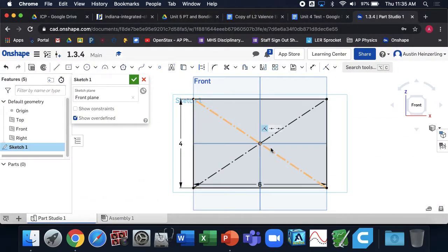How? Exactly, I just explained that. No, like, how to make the line? Yes, I just explained you could either draw a line from corner to corner, but you're like, oh crap, I don't want an actual line, so I'm going to select it and change it to construction. Oh, see, now that makes sense. The other thing you can do is say, everything I'm drawing right now, my construction line tool is activated, so everything I'm doing is a construction line. Bam. So I want these two diagonal lines.